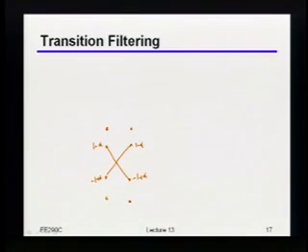Just as a reminder of what I mean by that, when we look at that loop-unrolled DFE with one tap, we said that there were multiple different types of possible transitions. As an example, you could have transitions that look like this, where this is the 1 minus alpha level, this is the minus 1 plus alpha. If you have a clock pattern, those would be the types of transitions you get, whereas in contrast, if you had something like a 1 1 0 or 0 1 1 type of pattern, then you might get transitions that look like this.